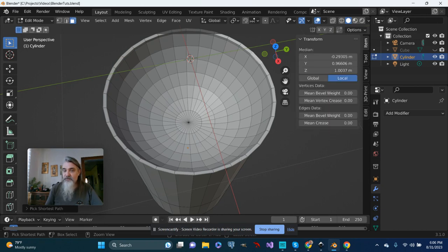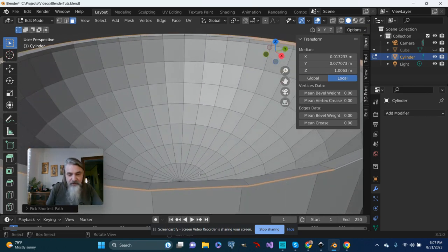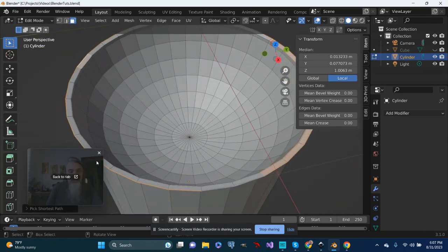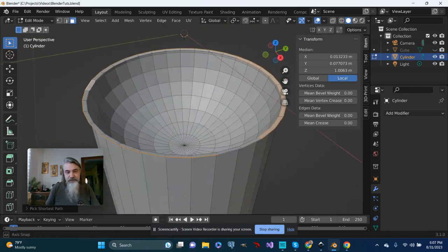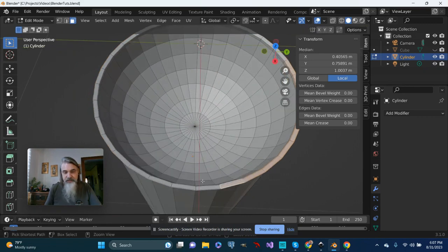Also, I have the ability to fill in all the gaps between the point that I previously clicked and the point I'm clicking on now. The only caveat there is that sometimes it will do something you don't expect because it's always trying to take the shortest path. So in this particular case, there's some very small faces here, of which there are only a couple. So rather than going across 1, 2, 3, 4, 5, 6, 7, 8, 9, 10, 11, like a dozen faces, it grabbed just like two or whatever. So let me just back up there and continue with what I was doing.